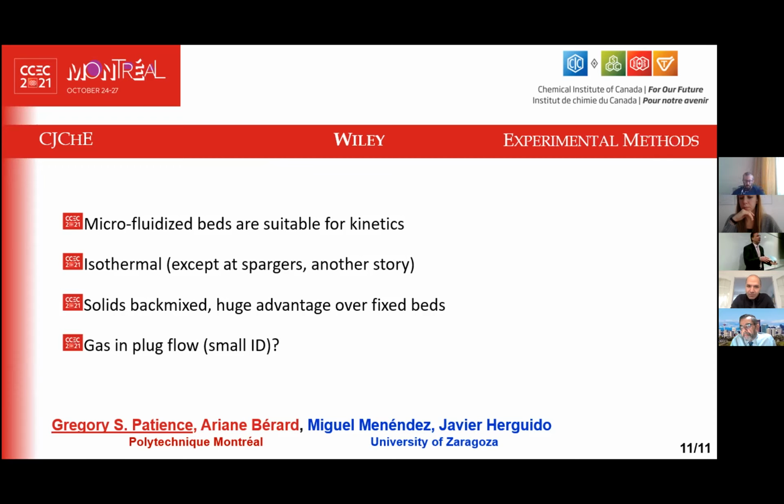So breaker bars, according to him and a lot of people, don't work, and the only way to control the plug flow behavior of a bed is with fines, meaning 20 to 45 micron particles, 30%. Great question. Okay, super.